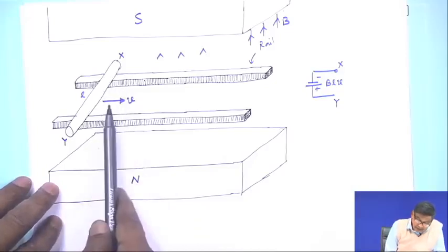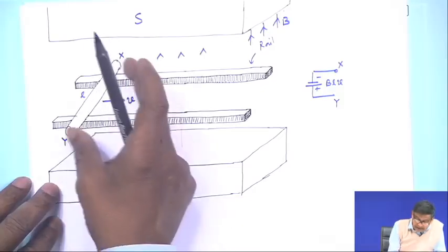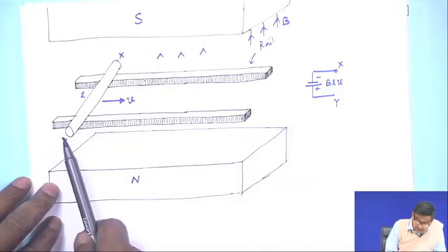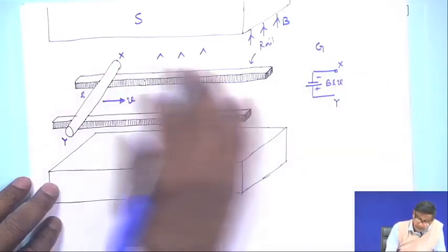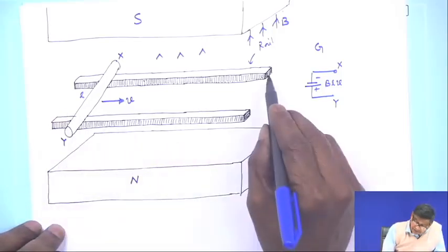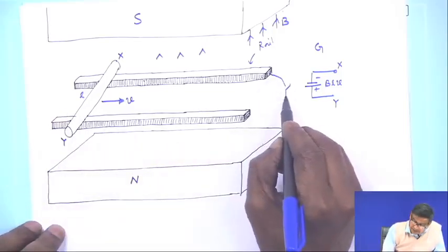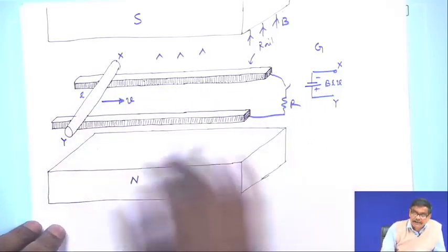Similarly, you see these are very interesting things. A conductor moving in a magnetic field has generated some voltage BLV with the polarity marked as shown. It is generator operation, it is moving. Now, why do we generate voltage? If you generate a voltage and keep it open circuited, how does it help you? You must connect some load across it. Suppose the load I will connect across this with a switch. I want to use this power, suppose it is a heater.